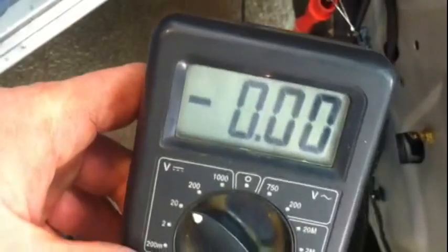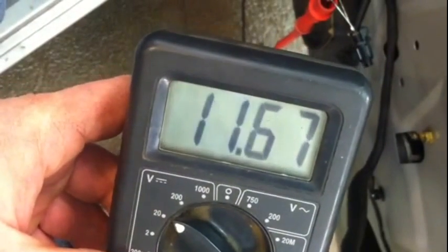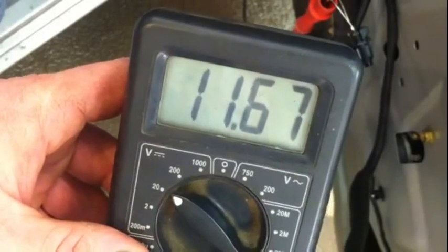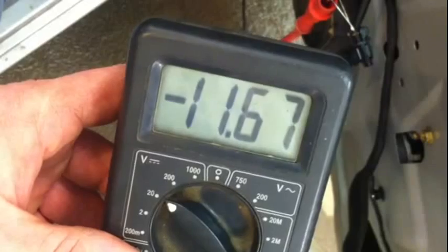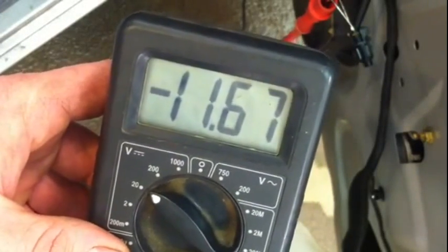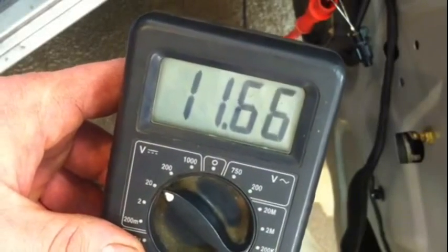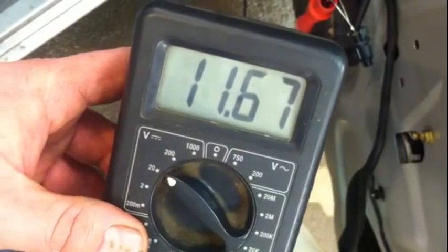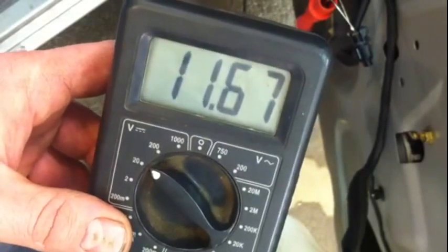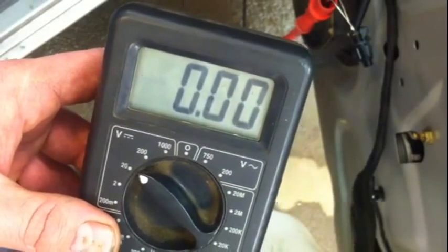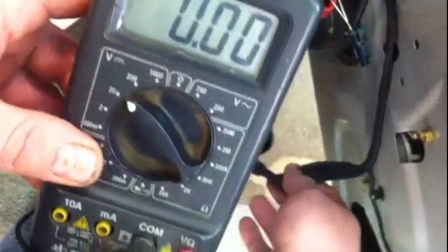Okay. Now watch. Like I said, we're looking for it to change states. So that's down. We have a positive 11.6 volts. Now we'll go up. We have a negative 11.6 volts. So this switch is actually doing what it's supposed to be doing. It's reversing the polarity, and it's sending enough voltage to turn this motor on. So now we'll do a voltage drop and see what's going on with this switch. As soon as I get set up for that, I'll turn the camera off here and we'll be back.